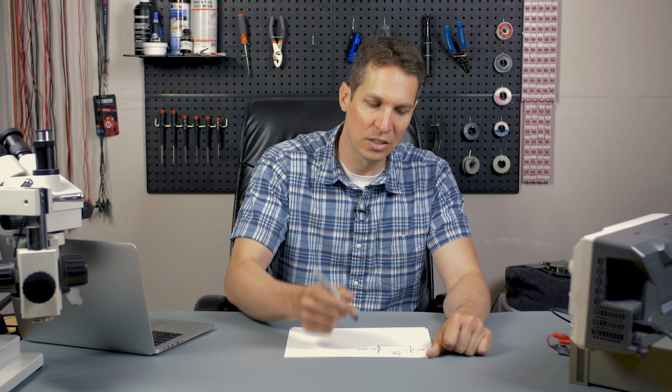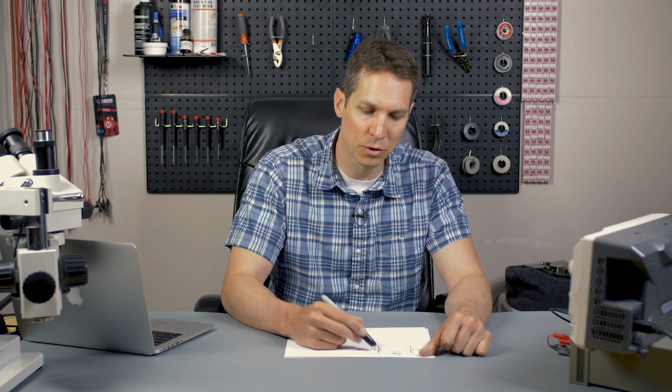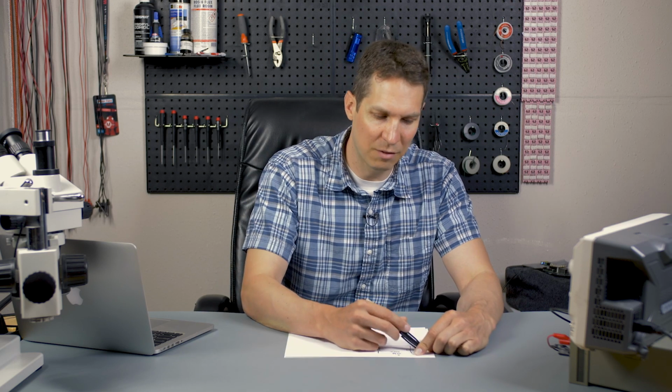Take a moment after you're done to look at it and say, does this make sense? Do these numbers make sense? If I have a 10-volt power supply and I see 100 volts over R2, where would that voltage come from? That doesn't make any sense. Obviously, I made some sort of mistake with my math. If I have a 10-volt power supply and I see 10,000 amps across it, like, okay, 10 volts using Ohm's law, that just doesn't make any sense.